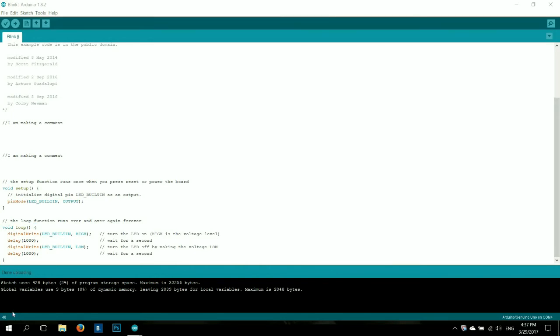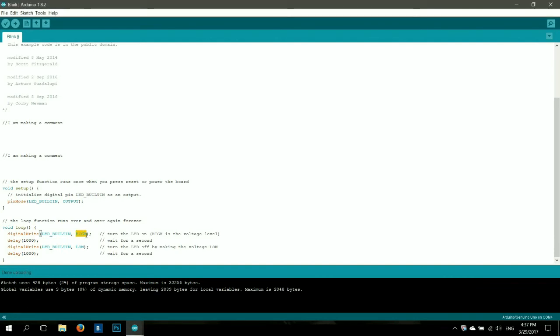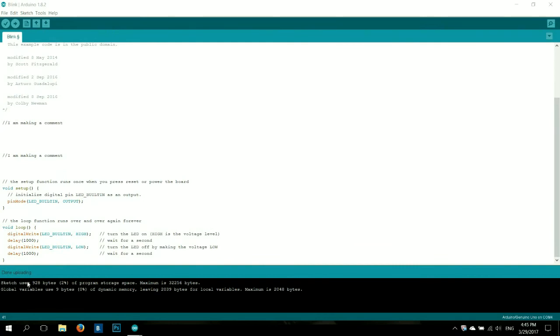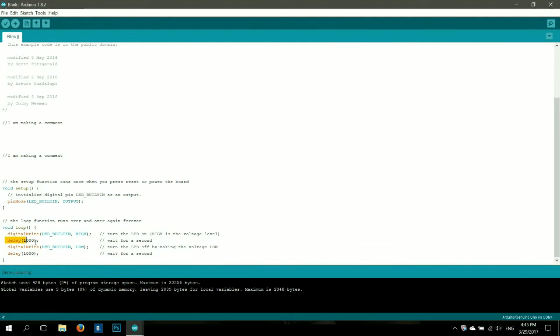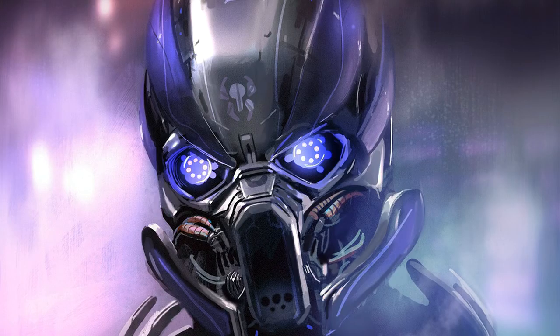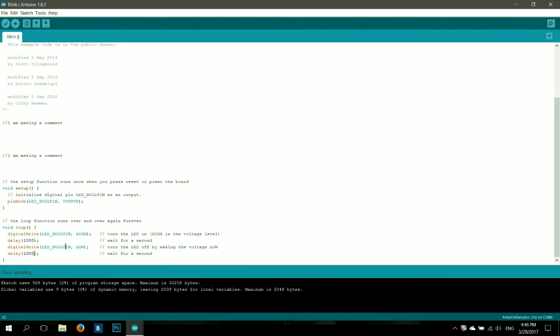This example makes an LED go on and off. This is done by setting a high electric signal via the processor pin to the LED to make it go on and an electric low signal to go off. Between these two signals there must be a time delay, so the human eye gets to notice the change in luminosity, otherwise it would turn on and off at the highest speed possible by the processor, and you wouldn't be able to see it. Unless you are a cyborg who can cope with such fast changes. I don't think so. Anyway, this is done by the delay function.